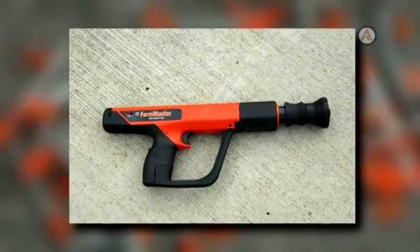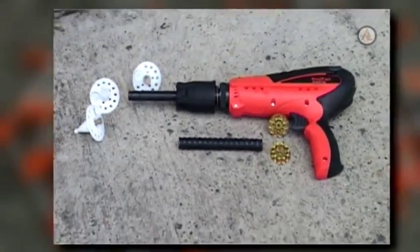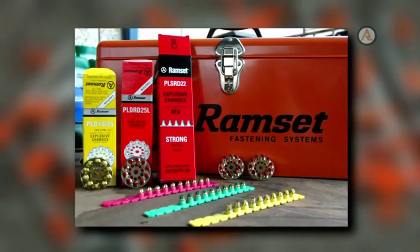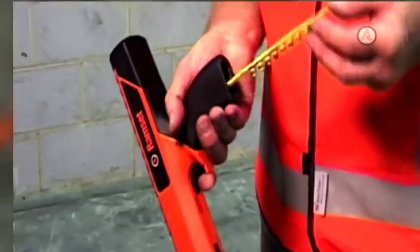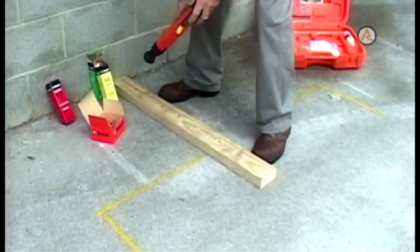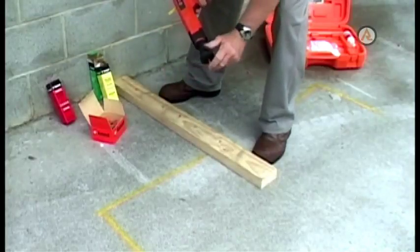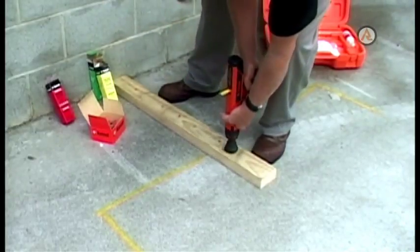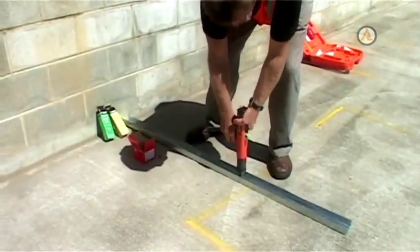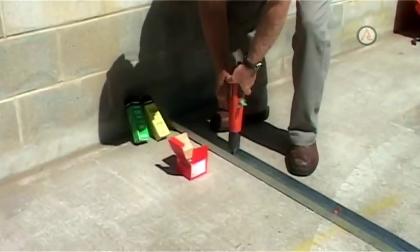There are now many different low-velocity tool models that range from simple single-shot tools to multiple-shot tools. In the case of multiple-shot tools, the power loads are collated in either a steel disc or a plastic strip. Low-velocity tool models also vary in the manner in which the captive piston is returned to the correct position for firing. Some tools return the piston as part of a manual cycling process, whilst other tools use an external mechanical steel spring.